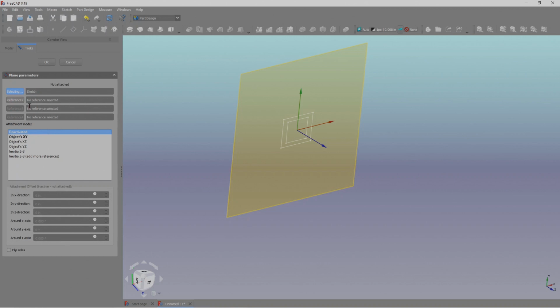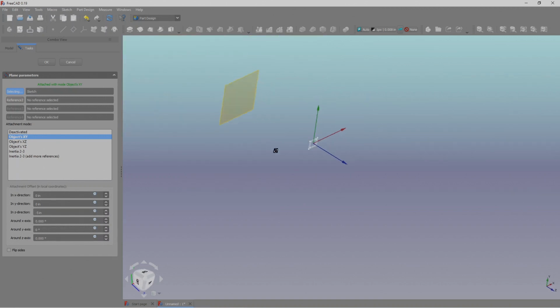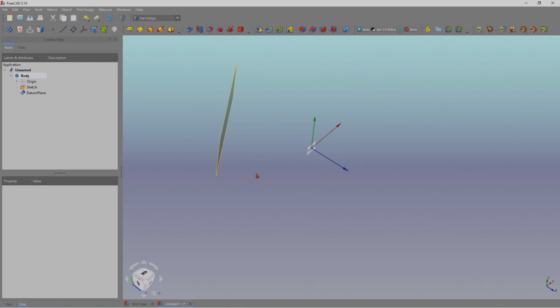It's because now it is activated, it's on the xy plane. I'm going to do some offsets here. So I'm going to offset it in the z direction in negative, say -5, and since y is still in this direction of this plane, I'm going to rotate it. Let's say I'm going to rotate it by 30. Okay, so I got a plane that is offset by 5 inches and rotated by 30.